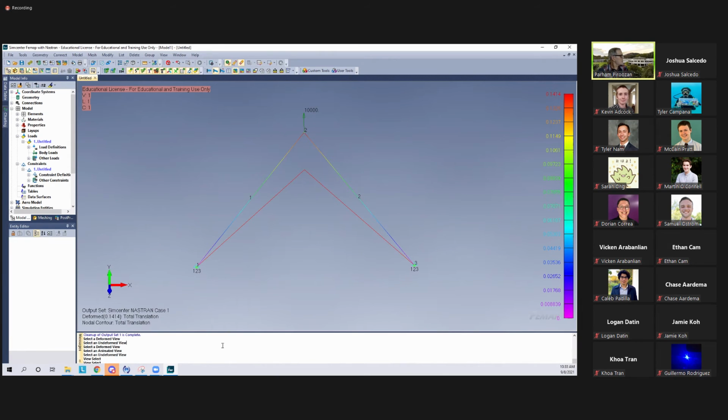So with this now, this is the plot of the results. I want to also do some other things. Let me show you one more thing before I let you do your work. I want to see the displacement table. I want to create a table and show these, for example, forces or stresses or displacements. To do this, you can go to List. I want to now show the displacements, numbers, and since I also have the exact solution, I want to compare to show you how it compares with the exact solution.